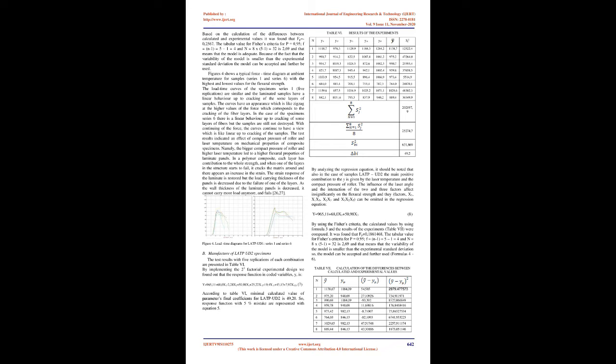Figure 4 shows a typical force-time diagram at ambient temperature for samples Series 1 and Series 6, with the highest and lowest values for the flexural strength. The load-time curves of the specimen Series 1, 5 replications, are similar, and the laminated samples have a linear behavior up to cracking of some layers of samples. The curves have a zigzag appearance at the higher values of the force, which corresponds to the cracking of the fiber layers.